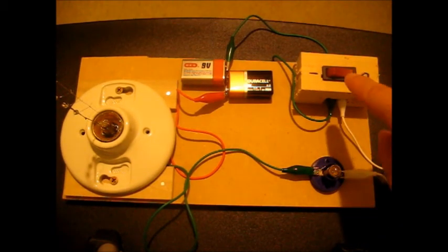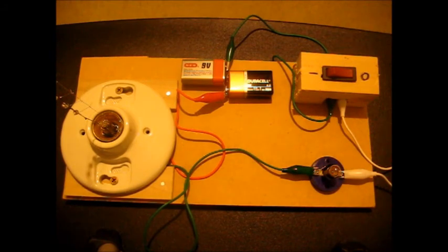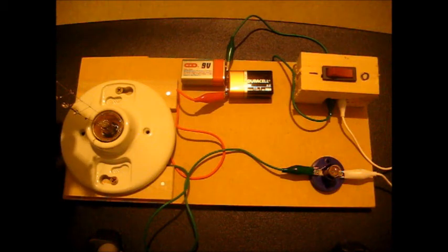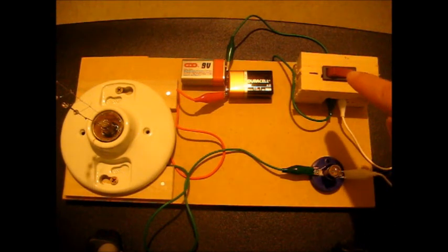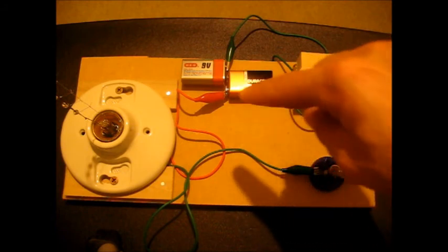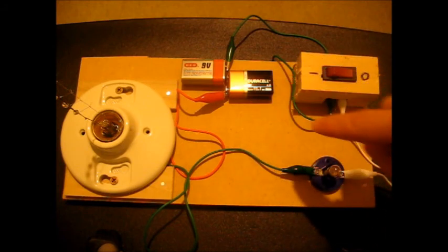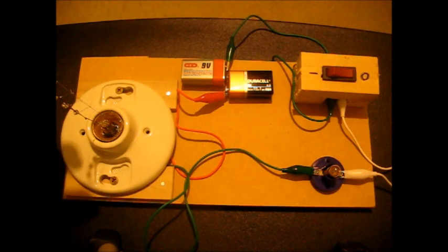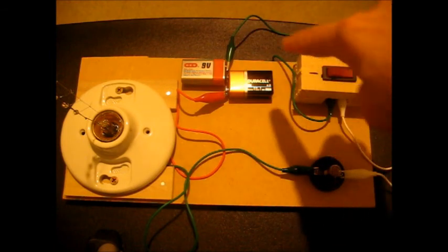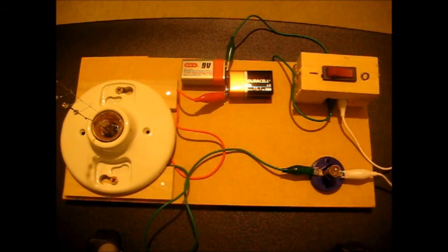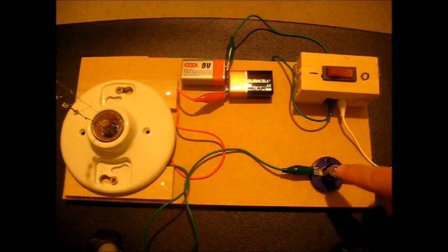When we turned the switch on, since at the beginning this high resistance bulb was cooler, the current flowing through the circuit was higher, and after a while this light bulb got hotter and its resistance increased. That's why the current flowing through the circuit decreased, and for that reason our little light bulb had less brightness.